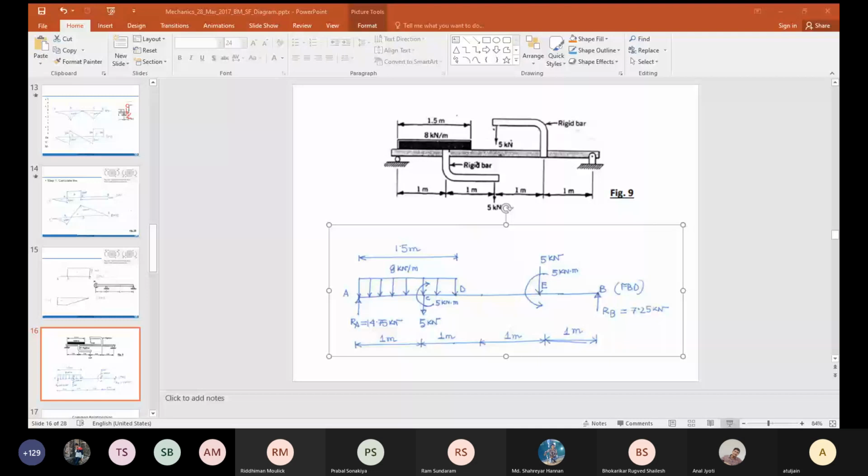Keep in mind that this bending moment that is applied here is also a load discontinuity. So I have to draw another section after that also. So 4 sections. It will take some time, but go for it. If you get this right, then more or less you can be confident about this, because this specific problem has all three together. All three as in all three types of loads.